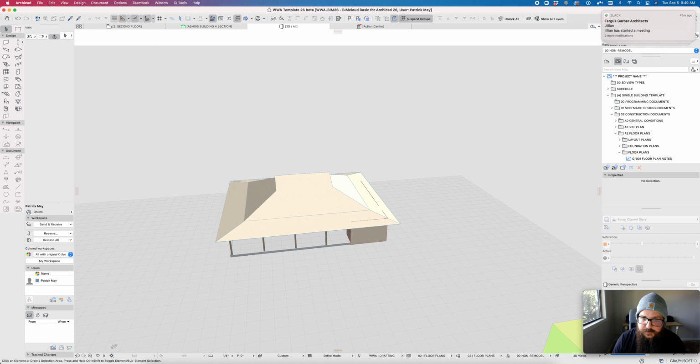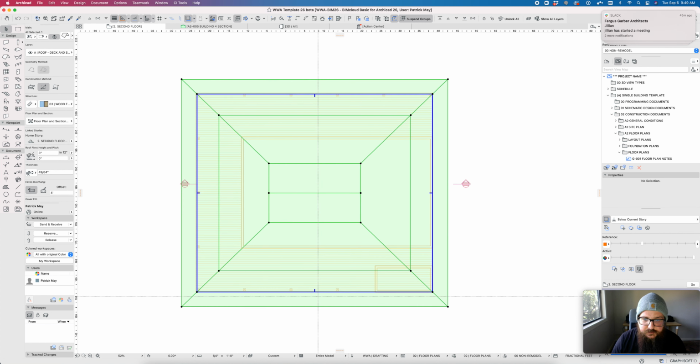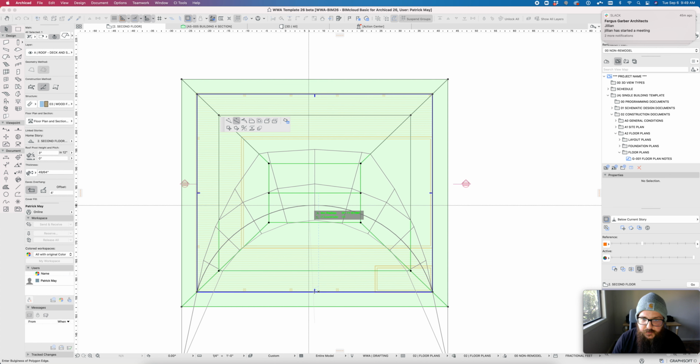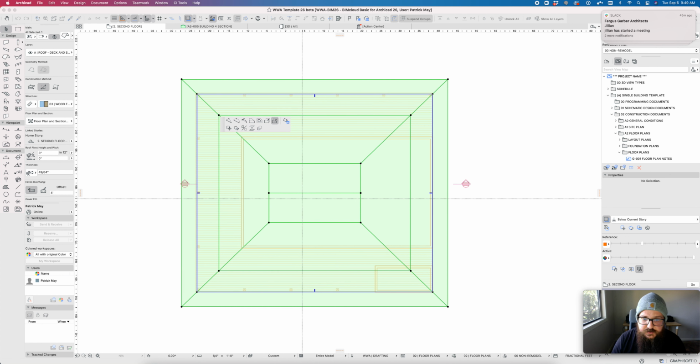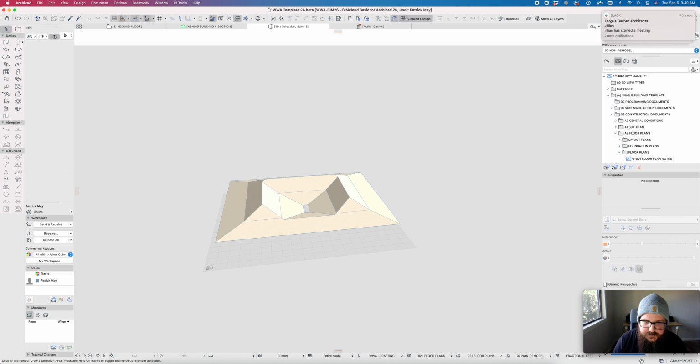Let's throw in a couple of shed dormers on the faces of these just to show you kind of how quickly this can work. So if you select the roof and you want to punch in an opening in the roof similar to what we were looking at with the slab, you can use the subtraction option. And notice what happens. I clicked on that blue line right here. If I draw in a square here, it slopes that inward, kind of creating inverted geometries sloping to that shape.